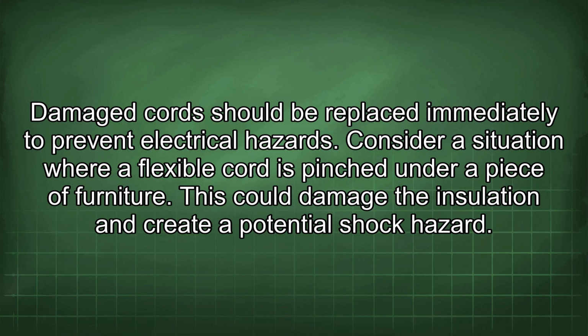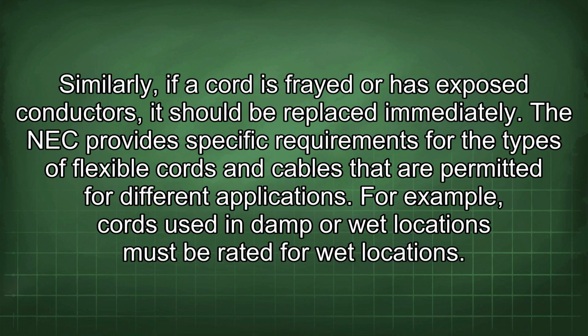Consider a situation where a flexible cord is pinched under a piece of furniture. This could damage the insulation and create a potential shock hazard. Similarly, if a cord is frayed or has exposed conductors, it should be replaced immediately.